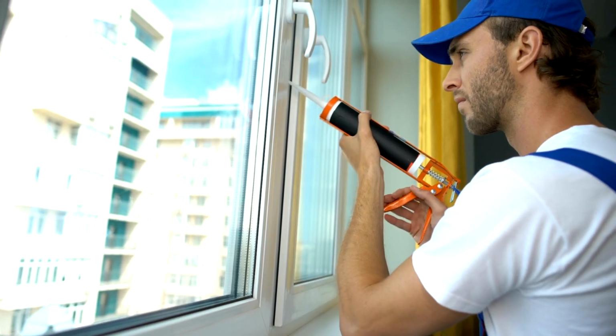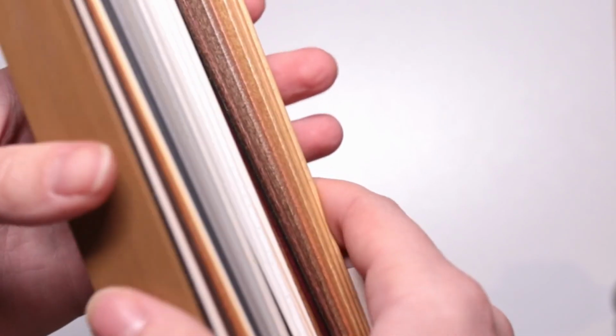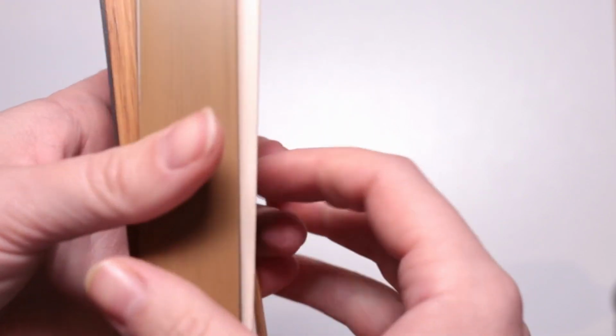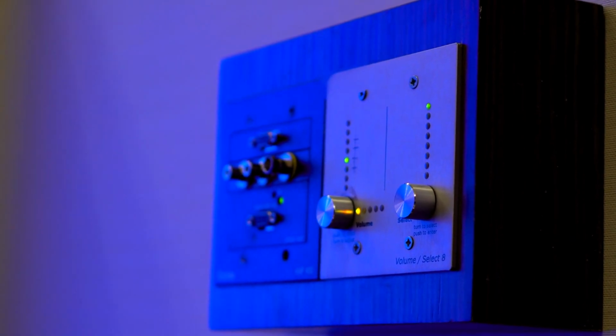Treating windows and doors. Windows and doors are common sources of unwanted reflections and noise leakage. Treating these areas involves both soundproofing and acoustic treatment. Thick curtains or blinds can help absorb reflections from windows. Adding an acoustic panel to the interior side of a door can reduce reflections and improve isolation.